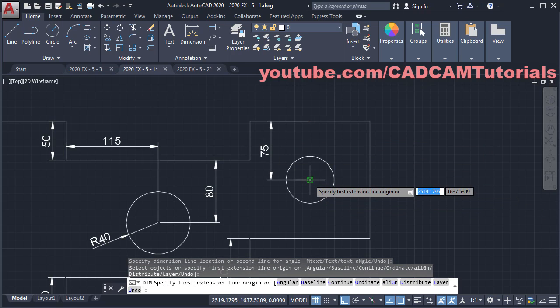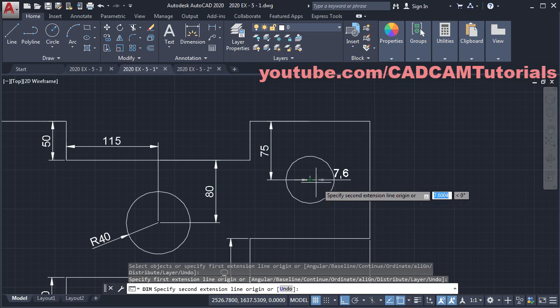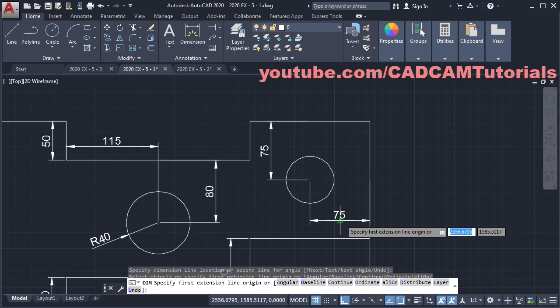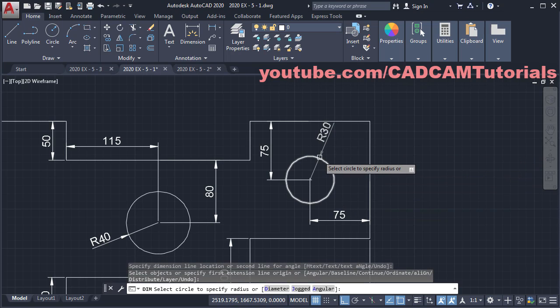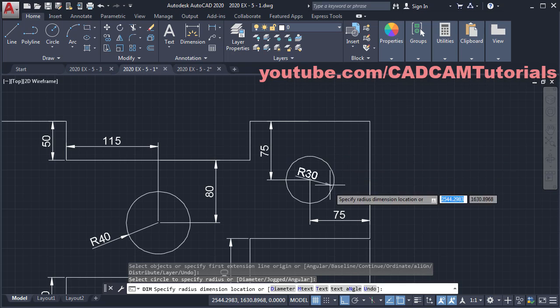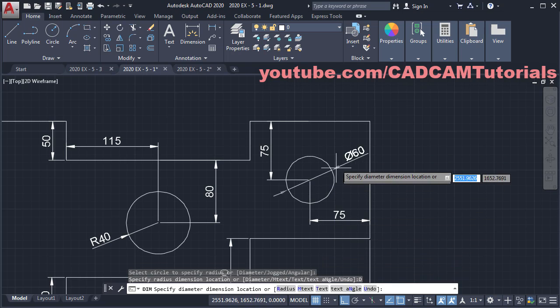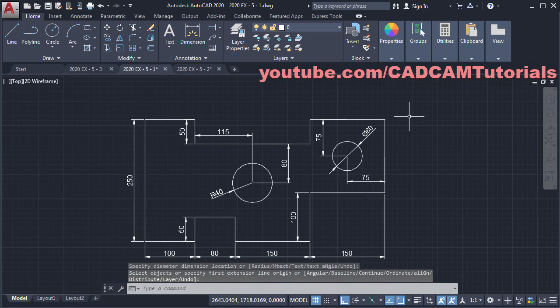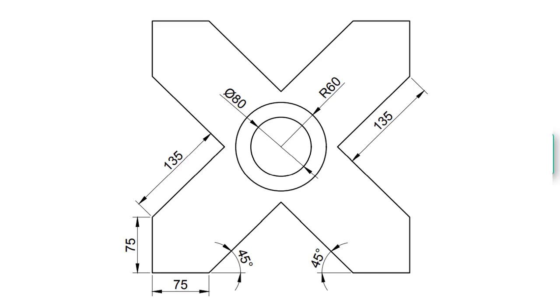Then again take your cursor on this node. Then click on this midpoint. Take your cursor below and click. Then take your cursor on this circle and click. Now we want to give diameter dimension here. For that, click on diameter and click and press escape. So all the dimensions have been given.